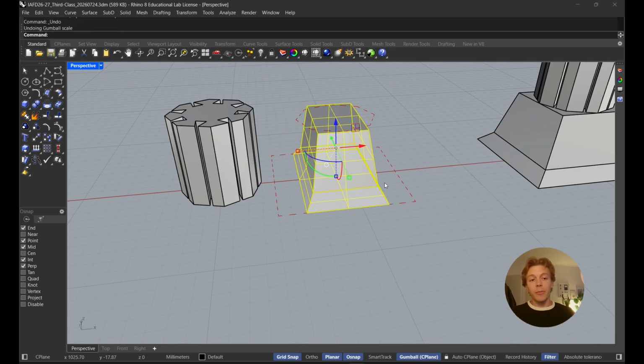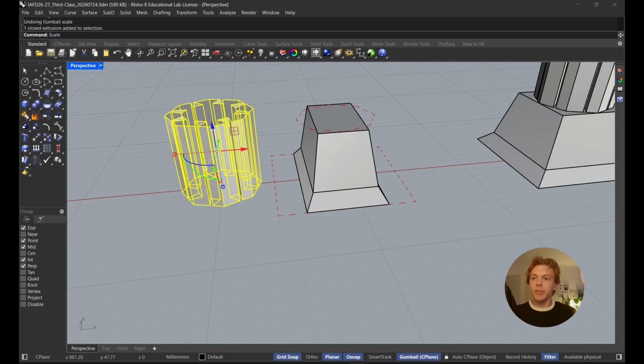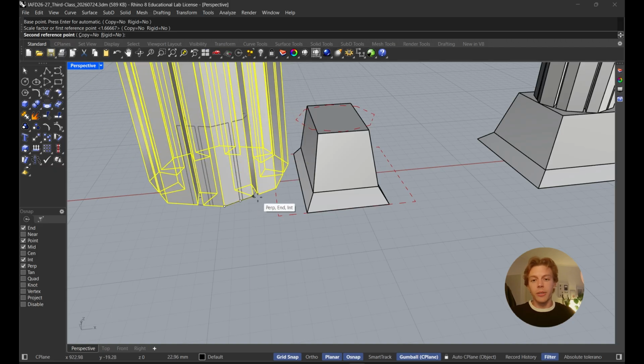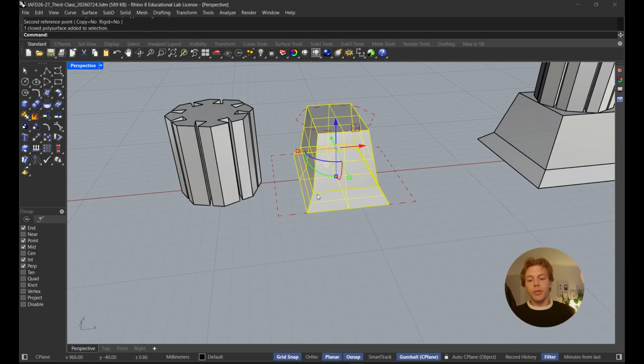So how can we fix that? Scale has three commands. There is scale by itself, which is all three dimensions. I'm going to show you quickly here, scale. So if I would like to make this bigger, I could do it like so with the scale command. There is also scale 2D, which is going to scale things in two dimensions, not all three. So let's try it out. Maybe this is the one that will fix our problem.